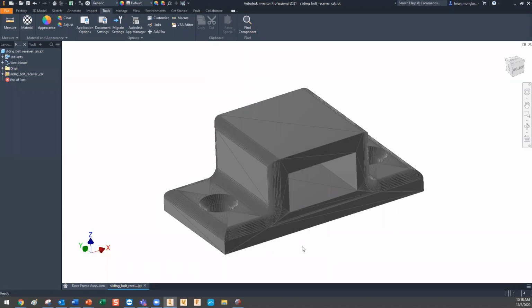So once you have that loaded, that gives you the ability under your mesh feature here, when you right click, now you have the ability to convert it to a base feature or a solid body. And in this little window, you have the option to convert it to a solid or surface, and you have the option to delete the original or not. The reason it's solid or surface is because if for whatever reason this mesh was missing a face, it wouldn't be an enclosed body, thus it'll be a surface, which is why they have the surface option. But if it's completely enclosed, then it should create a solid for you.